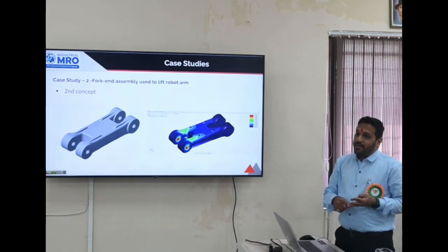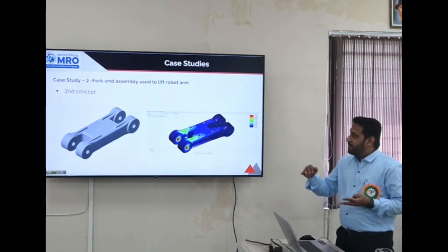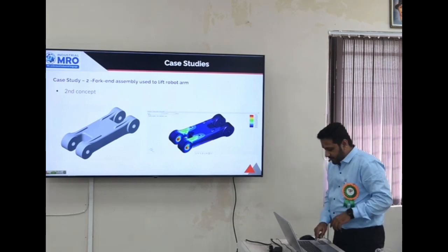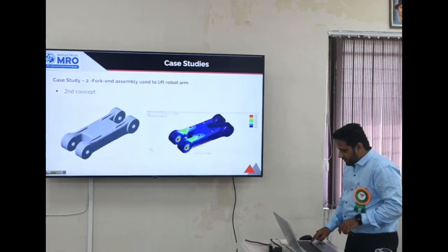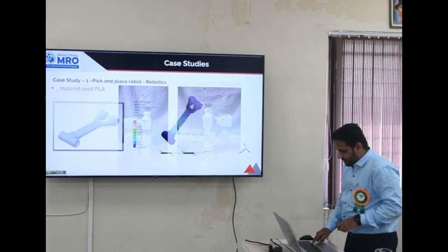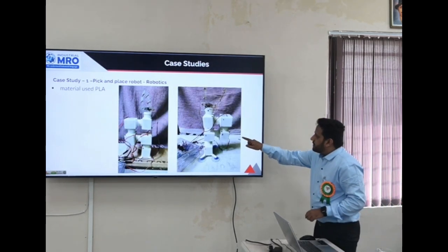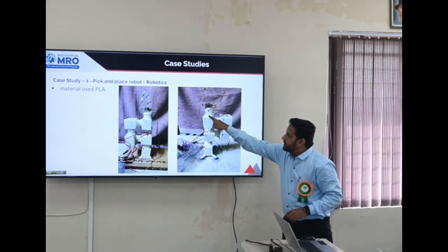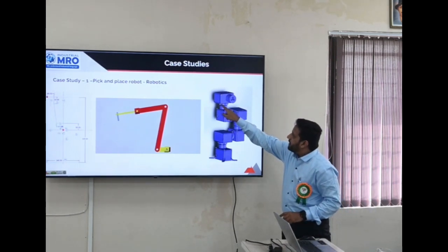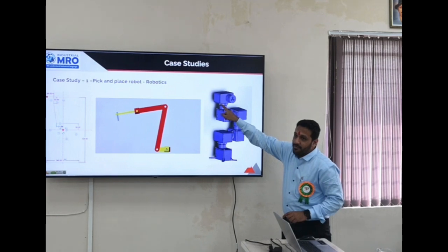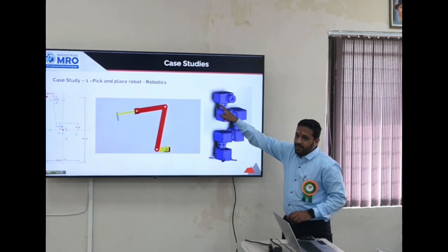And for example, if there is some overhang coming in, let's say this part, this region, if I need to add strength here, I will add more supports, so that when I am adding the supports in this region, it will be printed in a much better finish.